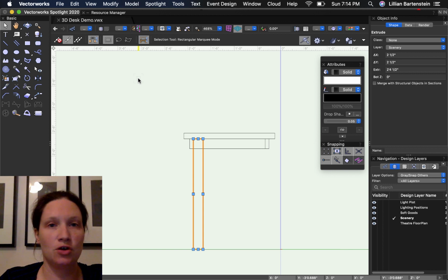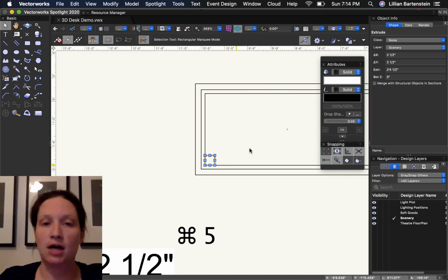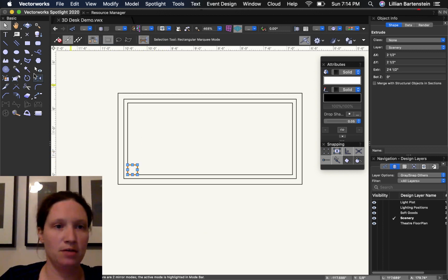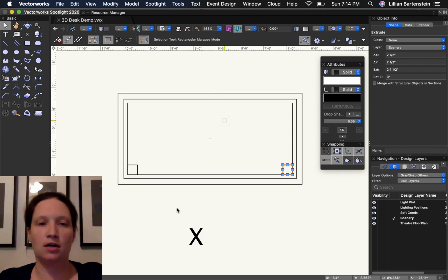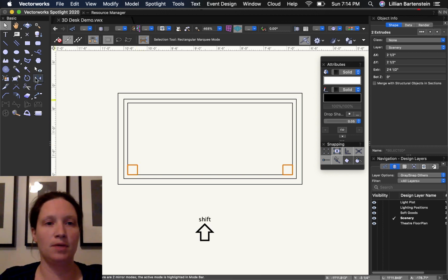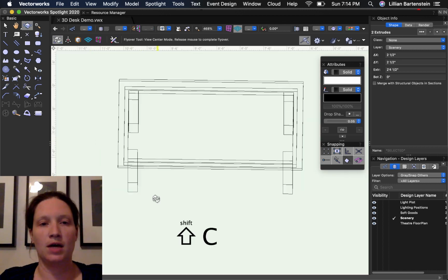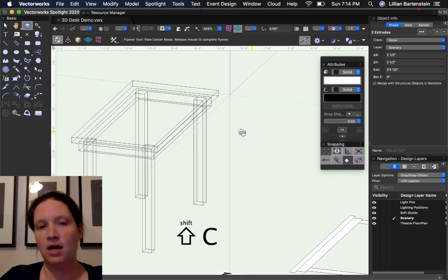I can also, from a top plan view, mirror an object like this, using basically the same commands I've been using. So I can say, go ahead and make a copy of yourself over here, right? I can now select the two of them and mirror that across the center the other direction. So as you can see, now the desk is coming together, okay?